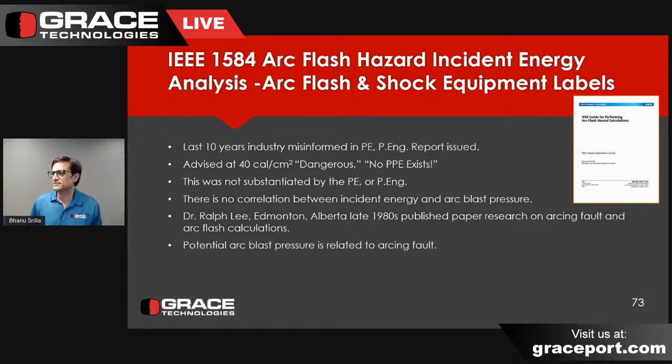So again, this whole thing with the 40 cal myth, and that was a question earlier, and I know there's been probably some more questions coming in, but the blast pressure has been miscommunicated. 40 calories per centimeter squared is not a dangerous energy level, and PPE does exist up to 140 cal. So every report that had this in it was wrong and misinformed the client that report was delivered to in the last decade, right? 140 cal suit's been available for the last 10 years. 100 cal suit's been available for the last 10 years. 75 cal suit, or 60 to 65 to 75, has been available for the last 5 years, right? There's no correlation between incident energy and arc blast pressure.